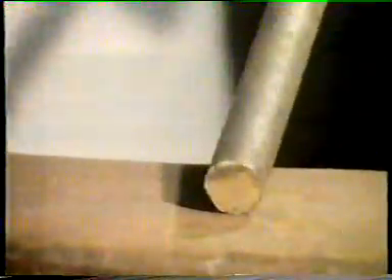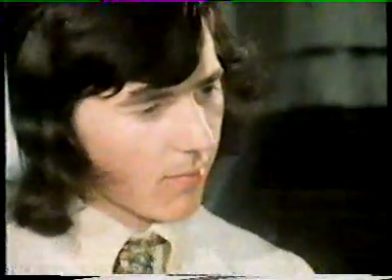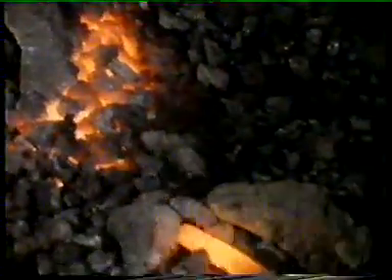This piece of cold, mild steel isn't a very malleable material. It can't be hammered into shape very easily. All that effort and hardly anything to show for it. In this forge, we've heated a similar piece of steel until it's a bright cherry red in colour. That's well below its melting point. Let's see if that's made any difference.